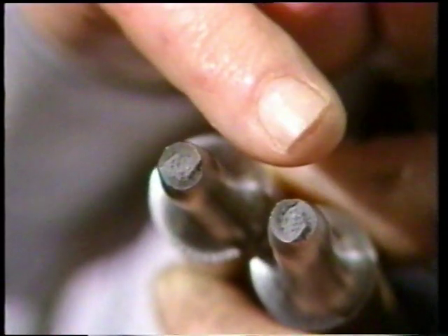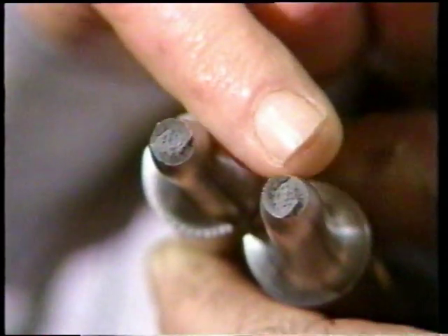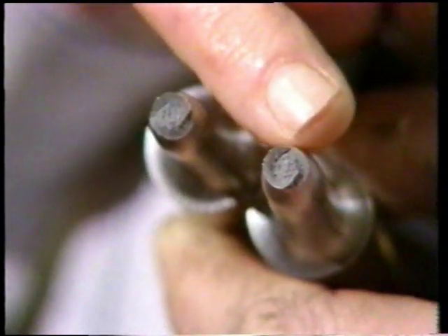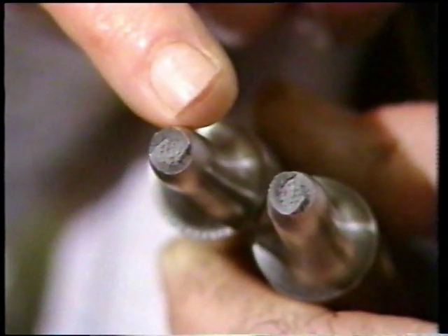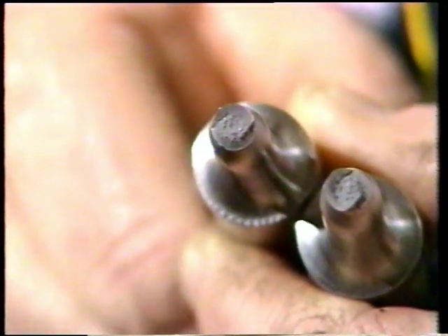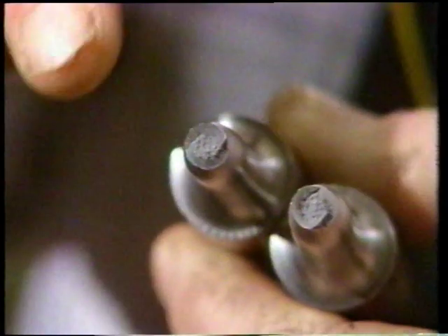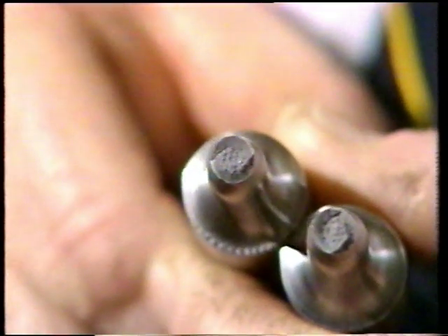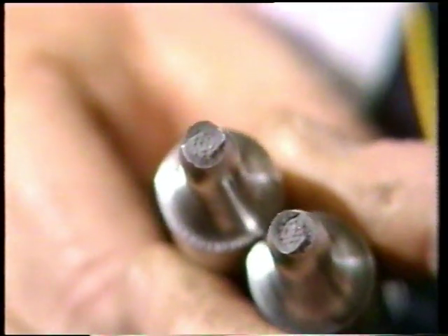Sometimes the lip is continuous around one side of the fracture. When that happens, you can easily see why it's called a cup and cone fracture, because we have a cup shape into which fits the cone on the other side. With a rectangular specimen, you get a similar effect, but the 45-degree lip follows the shape of the rectangle. But it's an indication of a ductile fracture in tension.